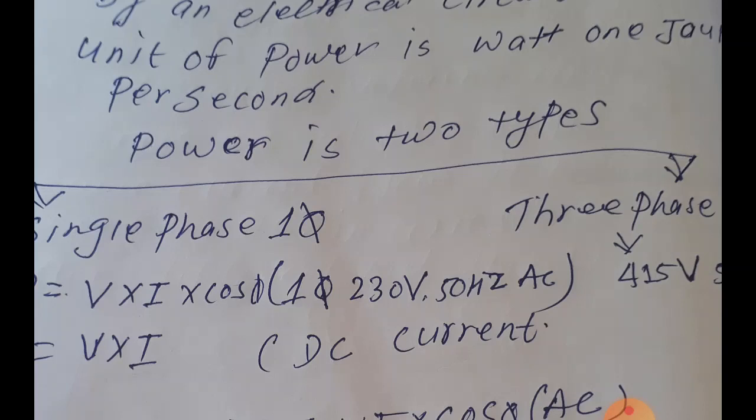Three phase is already coming to your distribution board, but one phase, the red phase, and one neutral are given to the lights; the yellow phase and one neutral are given to the power socket or AC; and the blue phase and one neutral are given to other equipment. So three phase comes in, but when using it we separate it, because these are very small equipment. But industries do not do it like that.